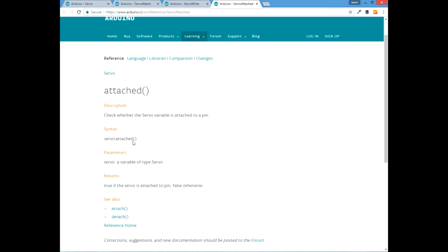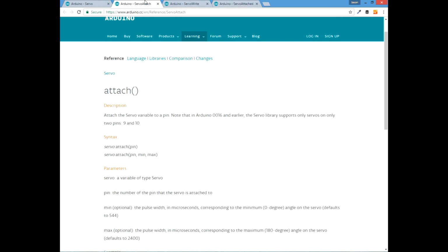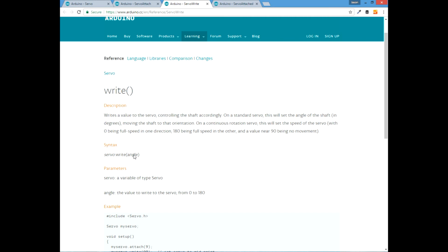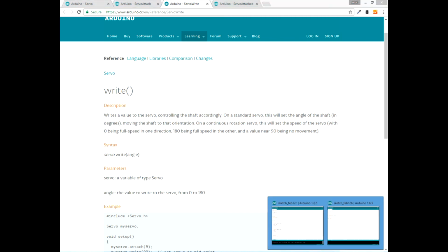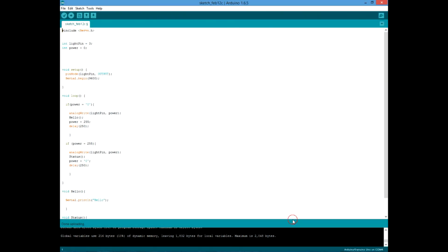You don't have to worry about any of that. It's just 2 commands, which is amazing actually. It saves you a ton of time. You load the library, then you write servo attach, and then servo write angle, and it will turn the servo to whatever you want it to be. I hope you can see how powerful that can be.